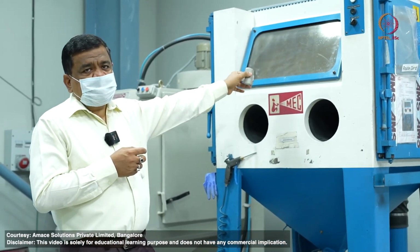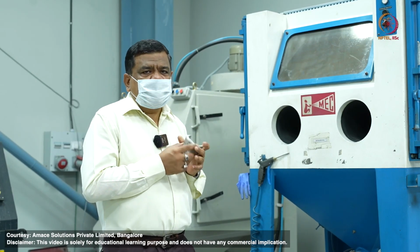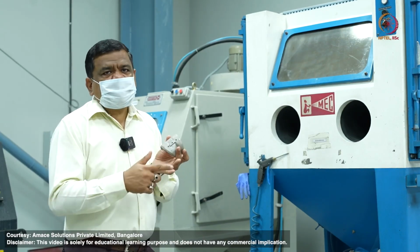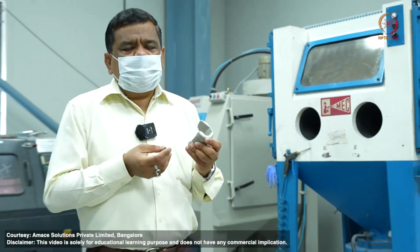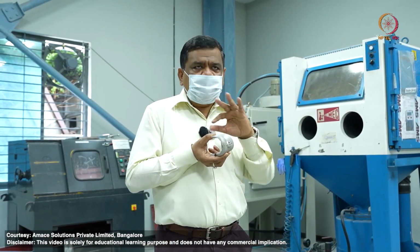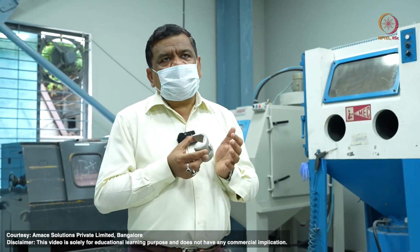This is the last stage of the post-processing step. In the grit blasting machines, generally 500 to 600 micron size stainless steel 316 grit is blasted continuously on the surface to make the surface smoother and to reduce the surface roughness of the as-built structures. And after all these post-processing techniques, if required, these additively manufactured components have to undergo further polishing to make the surface much smoother and also acceptable to the customer for the specific engineering application.